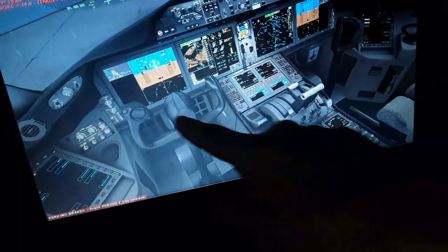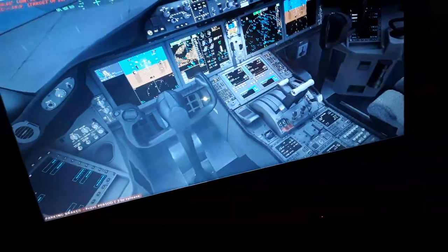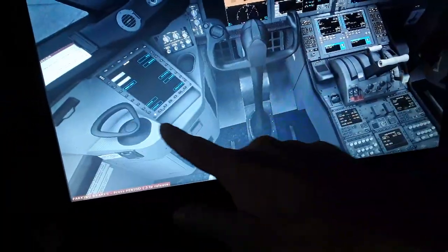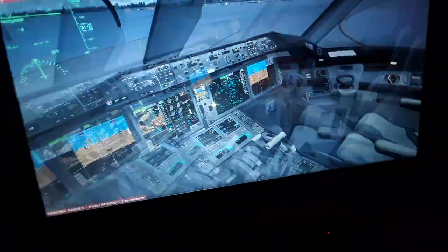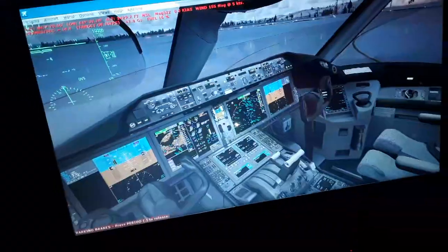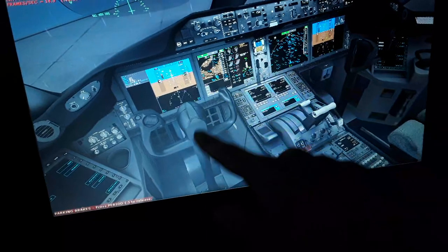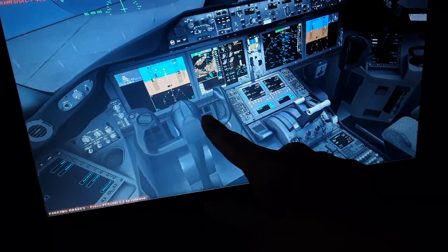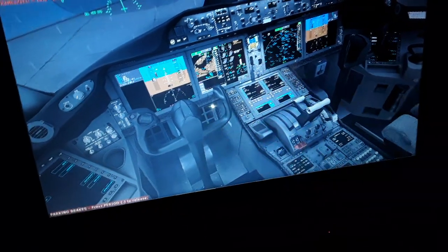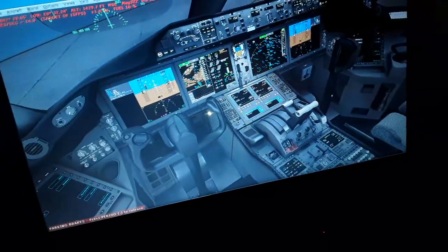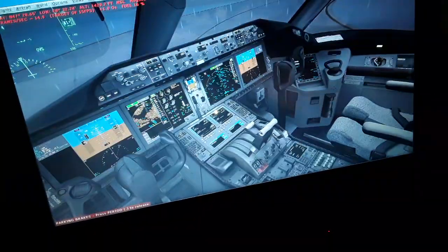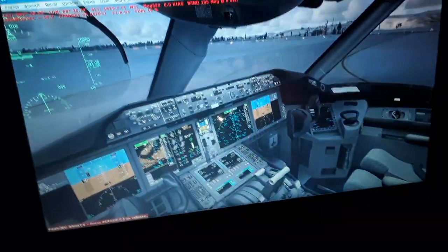Also we have the interconnected forward nose wheel of the aircraft. For the nose wheel steering we use the tiller on both sides in this aircraft, the Boeing 787. So we control the rudder on the vertical stabilizer, and the nose wheel steering. Also the toe brakes, we can brake the aircraft. We press the toe brakes on the top surface of the rudder pedals.